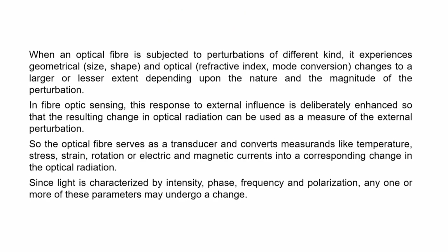Now, of course, when an optical fiber is subjected to perturbations of different kinds, like a geometric change or an optical change, then the nature of the wave that you are getting at the receiving end, from the transmitting to the receiving end, will change. The intensity will change, the modulation will change. So, that can be used to measure the external influence.